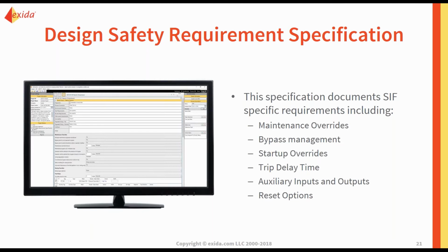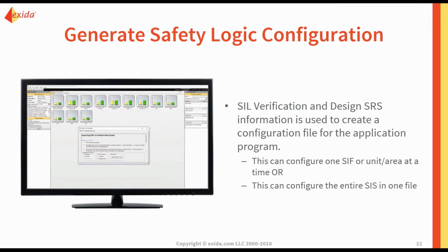And finally, when all of this is done, when you've completed your SIL verification and you've completed your design SRS, you can generate a file from exSILentia that can be used to create a configuration file for your application program. In this case, we're talking specifically about DeltaV.